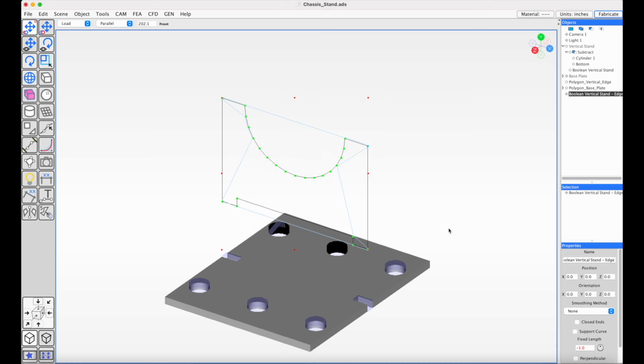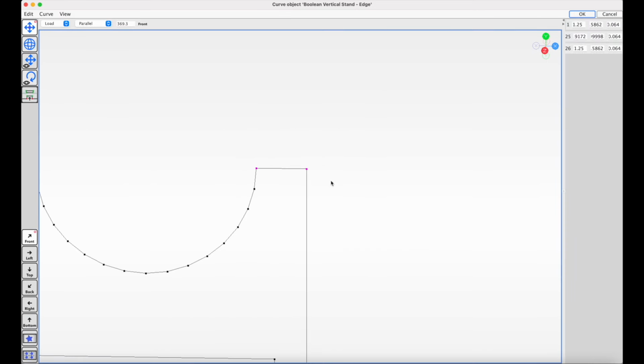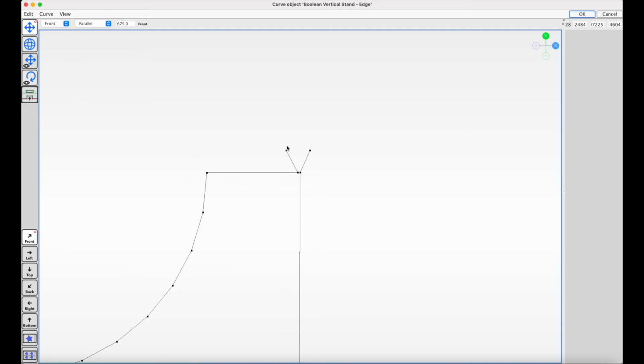It will also add lead in and lead out start and end points so that when the plasma torch is initially piercing, it takes a small amount of time in order for it to ensure that there's an arc, and that can create a hole in the part. It's a good idea to outset that so that the hole happens outside of the part. If I go to edit, I can see, and I can also manually edit these lead in, lead out. But the G code generated will start here, run through the part, and then end.